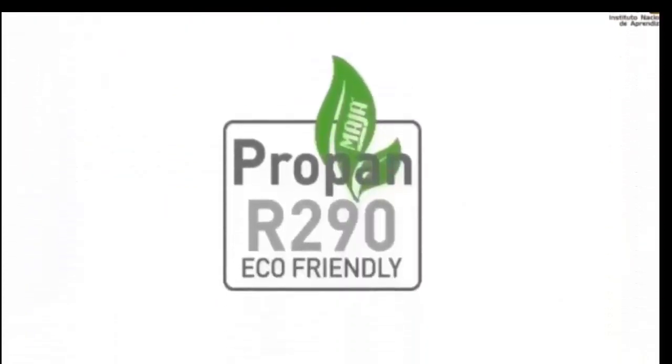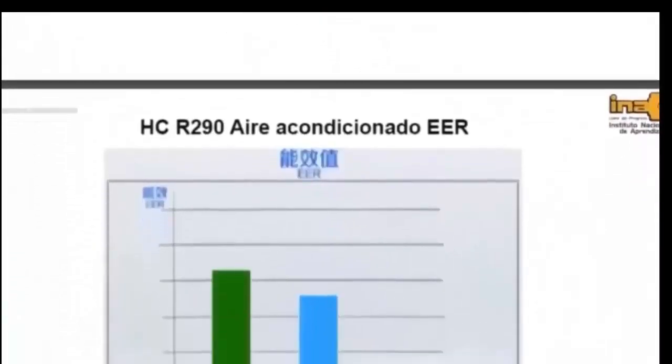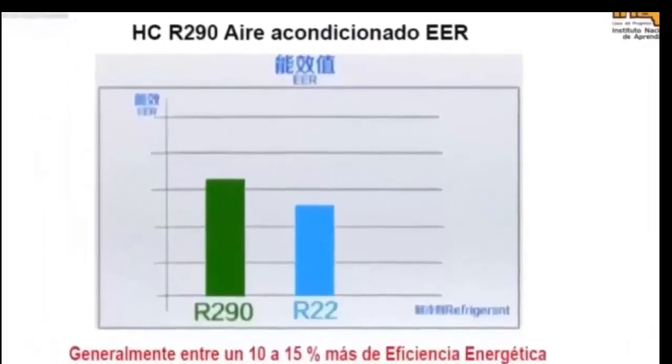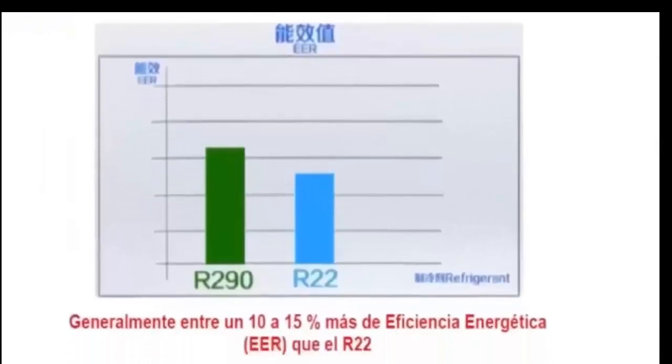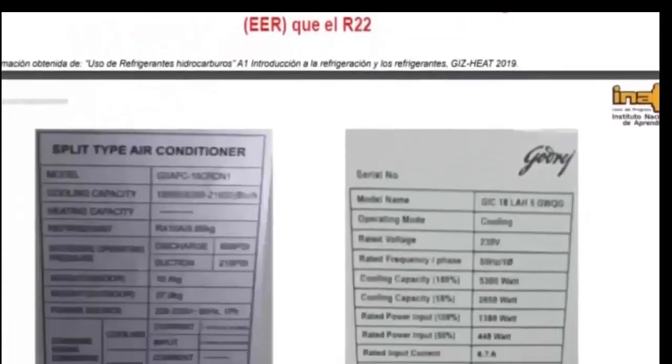16. It is very important, when working with refrigerants of the hydrocarbon type, that these are of high purity, since any proportion with other impurities, such as sulfides, water, etc., can contribute to the degradation of the lubricating oils of the installation, rupture of compressors, etc. 17. As a team, it should be avoided that the evaporator, the thermostat, or the switches are in the same cabin.